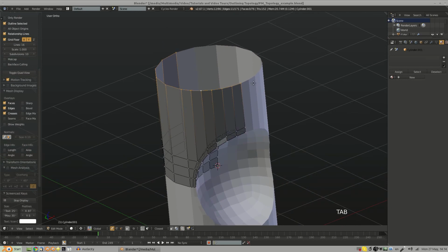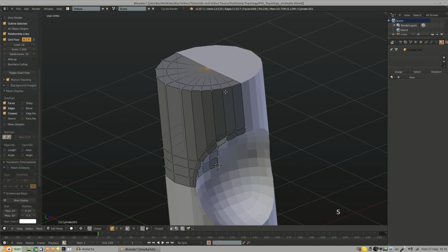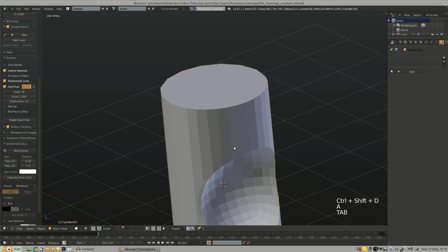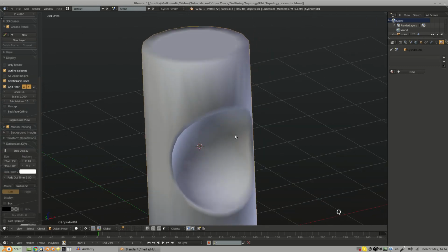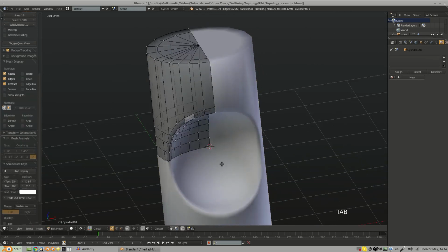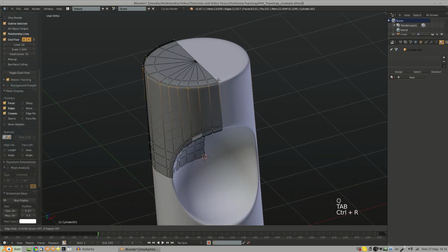So I'll just close this off, and I don't really care about the triangles in this case because it's the top of a cylinder, so I'll just remove those doubles, and there we go. So if we shade this smooth now, we should see a few, oh, I was expecting some normals errors because I always get them usually. And then add our subsurf, sharpen this up,